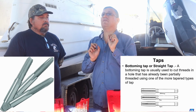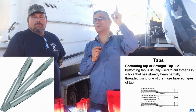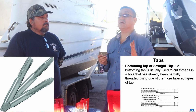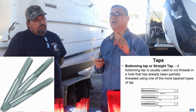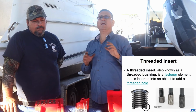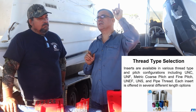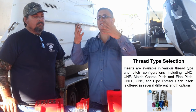Each hole takes three different types of taps: conic, semi-conic, and straight. This is the procedure we are going to practice in the laboratory for that project. Another project that we are going to do is insert the helicoids. When the thread is completely damaged, the only solution is to make a bigger drill hole and install a helicoid. And yes, we are going to do that process in the laboratory.